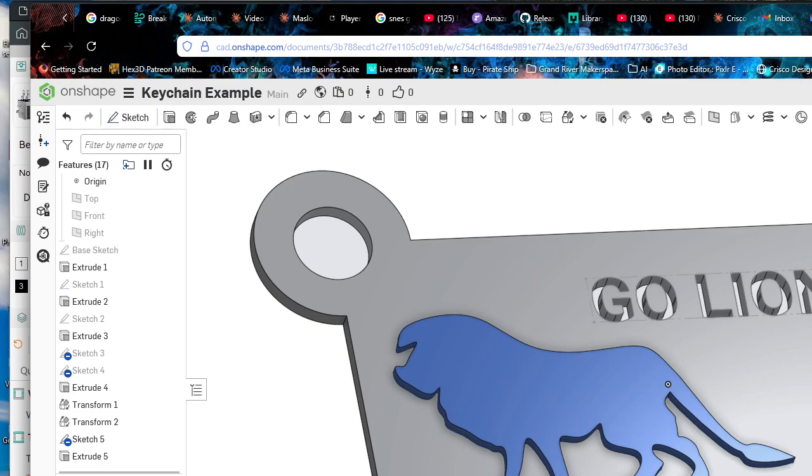The issue is that this DXF image, is it easier to make it smaller here? Yes. The other way I've done it in Onshape when things don't import right is make a 3D body out of it, and then you can scale it down until it looks right. Okay. Let's see if we can put it.